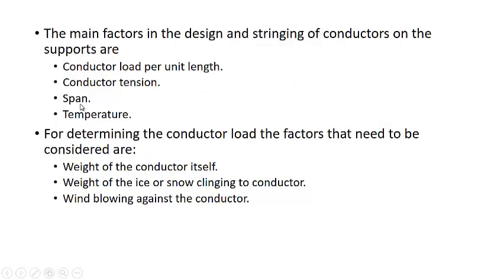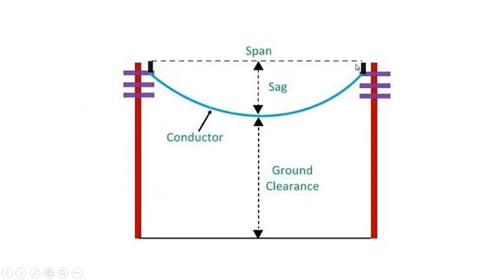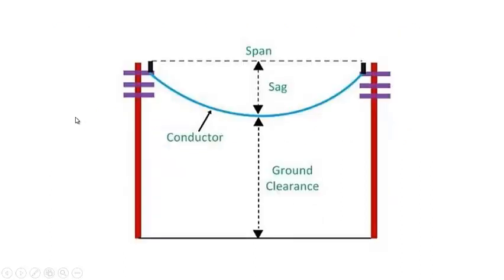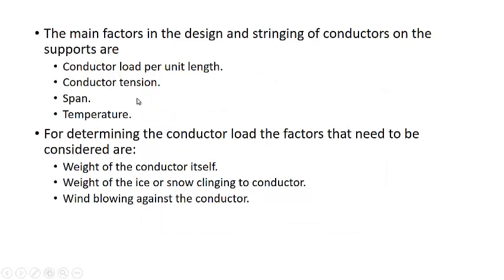The span. Span means the horizontal distance between the two supports, and temperature. As temperature increases, you will see that the sag will increase. The length of the conductor will increase and its tension will decrease. We'll come to this after completing these things.